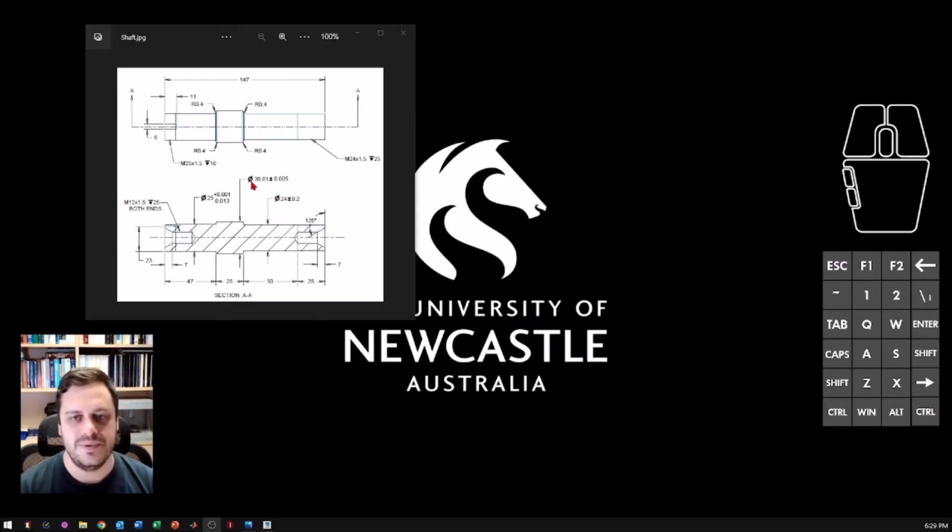One thing to note on this particular screen, and this is something you'll go through in a few weeks' time when we talk about section views, especially with your technical sketching portfolio, is you'll have some dashed lines that you can see on the top view, and then I've got my little AA. That's indicating a section view where it's cut through that part of the shaft itself. With a section view, it's effectively imagining that you're physically cutting the object wherever that section line is shown. You can see our section view down here indicated by section AA, with the hatched lines. So you imagine if you get a saw, for example, and cut through the object, it would leave those sort of lines, and that's why we call this a section view.